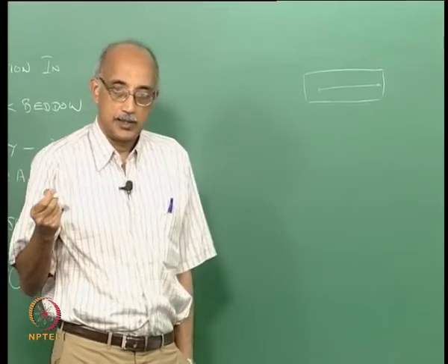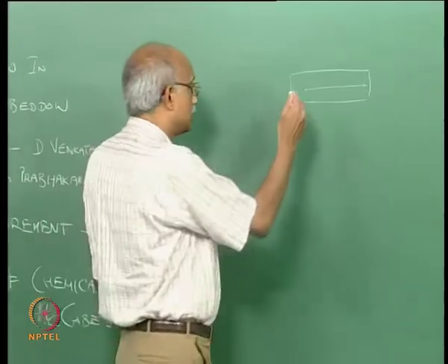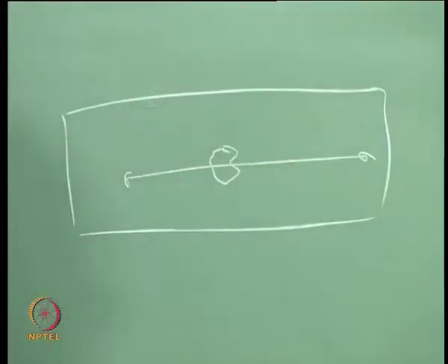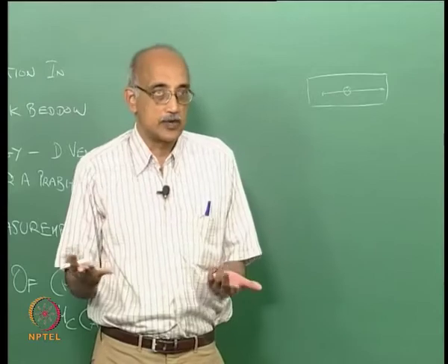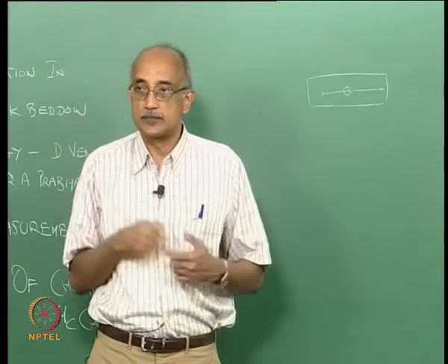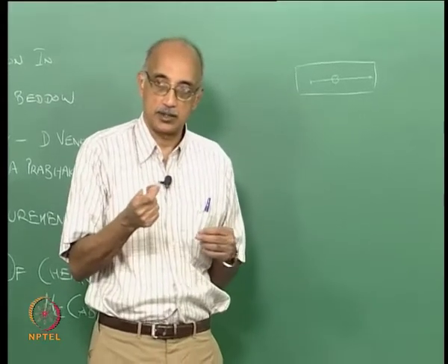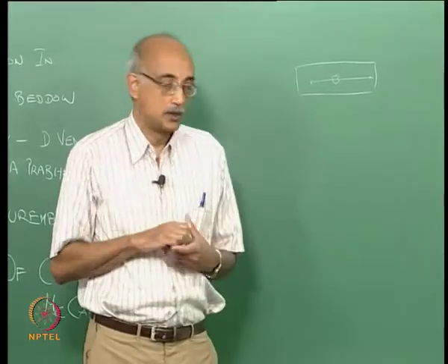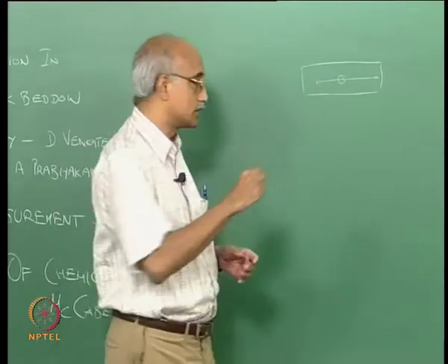Supposing an insulating particle drops into the middle of this conductive section. This could be, for example, a plastic particle, or even something as simple as clothing fiber or human skin or hair, which is essentially non-conducting compared to the metal conductor that the device is based on, what that's going to do is essentially short this circuit.